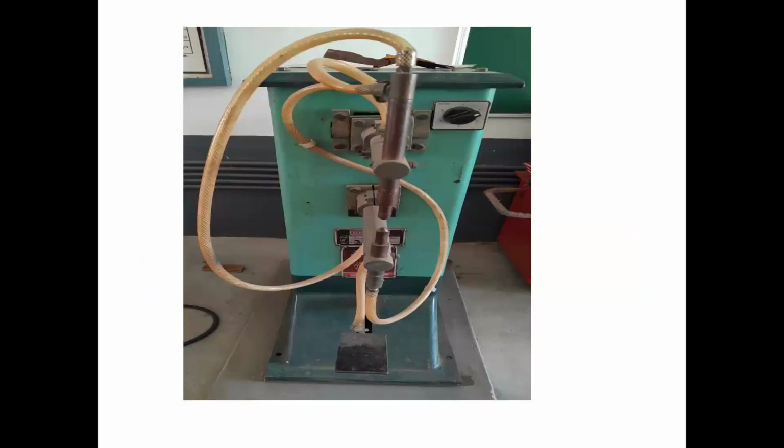This one is our laboratory setup. We observe this one. We can have some upper electrode, lower electrode, and I can place some metal pieces here, workpieces. Then I can use only the sharp edge at the joining. But I'd like to apply some pressure across this one. There, these two workpieces will join only at some specific point, spot.